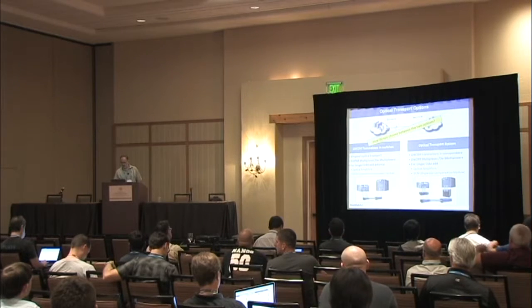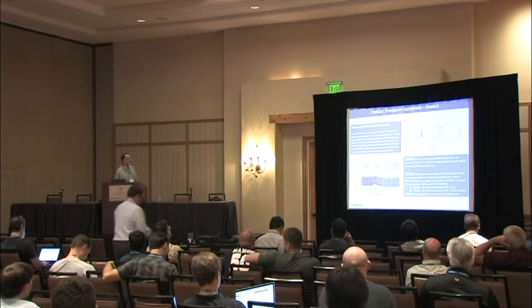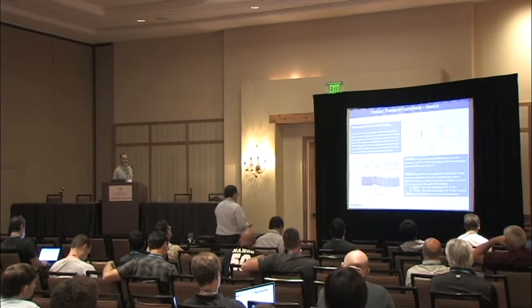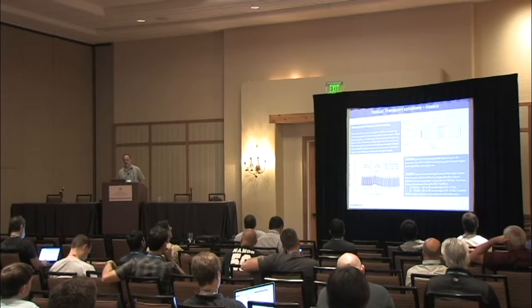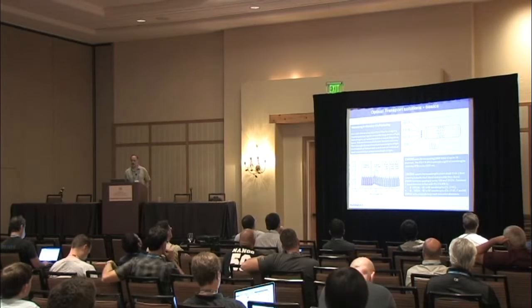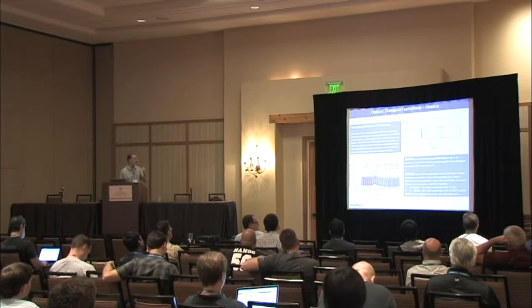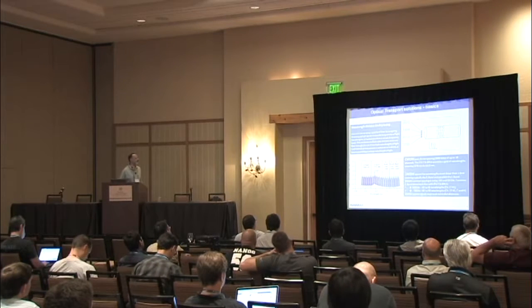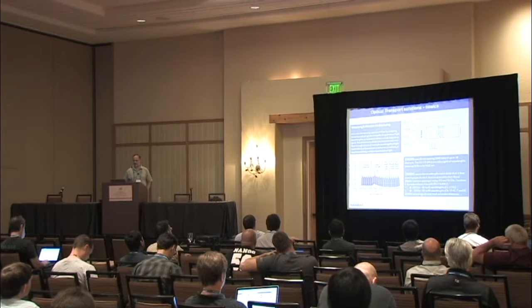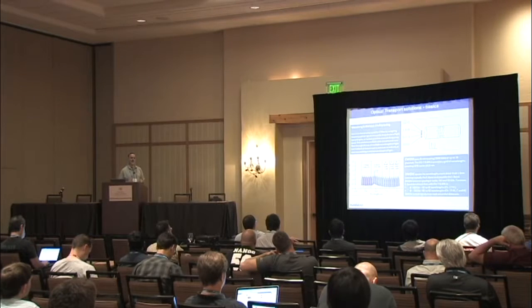Okay, thank you. So just going over the basics of optical transport, defining wave division multiplexing. That's basically a method of carrying more capacity over a pair of fibers by assigning the incoming optical signals to specific frequencies of light. Those are the wavelengths or lambdas. And combining those streams together generates more bandwidth. And every data stream has its own virtual fiber, its own virtual lambda.